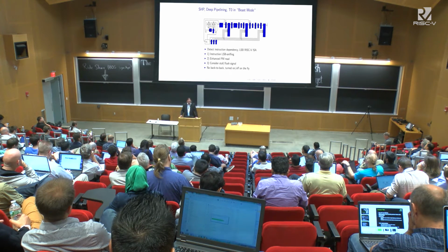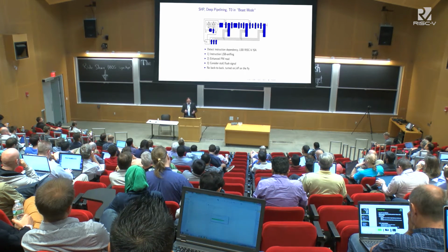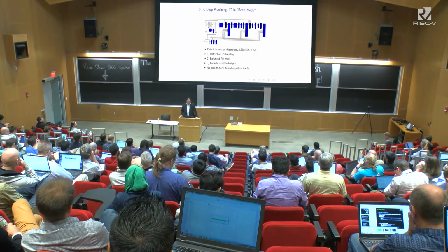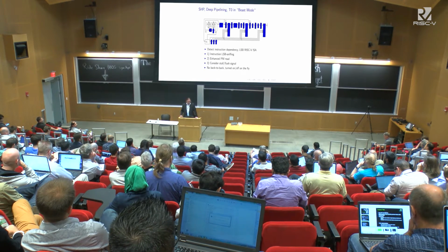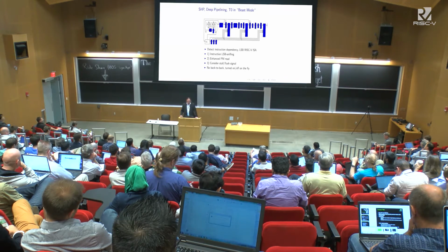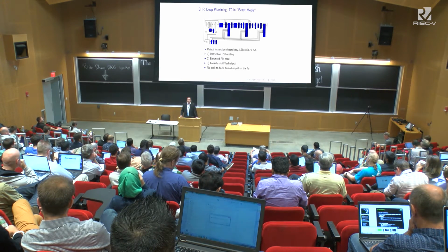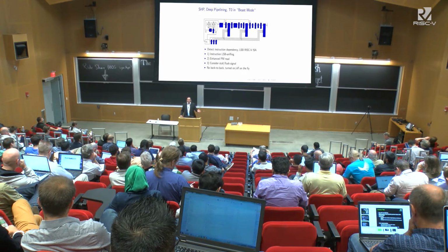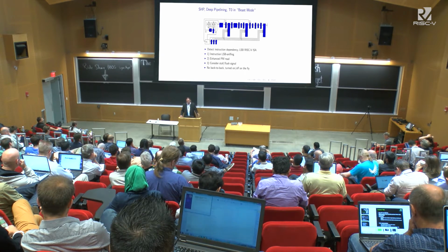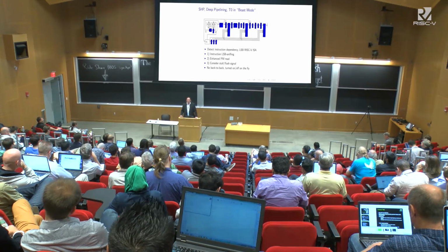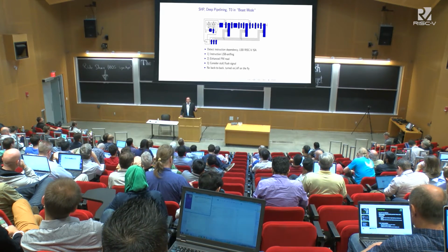So you implement a kind of instruction least significant bit sniffing. You enhance the program memory read, and you still have to consider stall and flush signals. I wasn't able to run back-to-back instructions, but it works with every second instruction, and you can turn on and off this method on the fly.